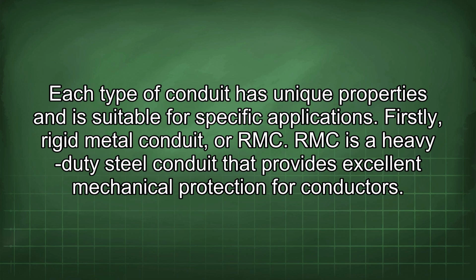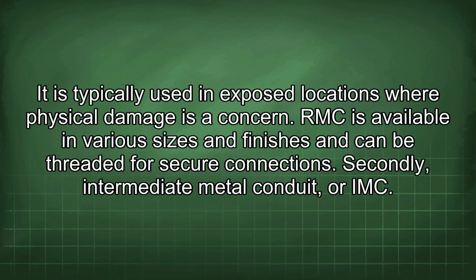Firstly, rigid metal conduit, or RMC. RMC is a heavy-duty steel conduit that provides excellent mechanical protection for conductors. It is typically used in exposed locations where physical damage is a concern. RMC is available in various sizes and finishes and can be threaded for secure connections.